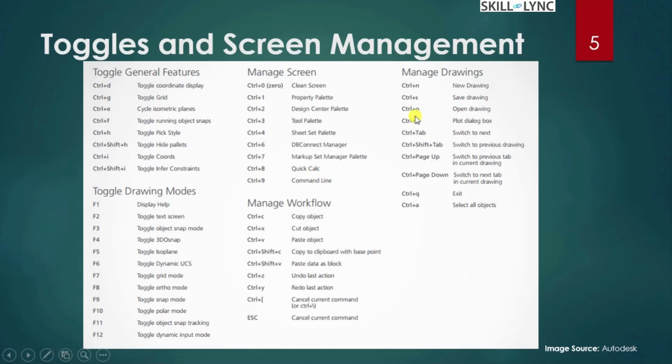And likewise, in order to switch between the different drawings, instead of selecting them manually, you can use Ctrl+Shift+Tab, Ctrl+Page Up, Page Down to cycle between the tabs that are available in the drawing. So next, again, the drawing moves that we saw in the one-key shortcut, and again in workflow for quick copy paste. So these are all overall workflow. Inside the drawing we still have the move option or cut option, undo option, all these things, but still we can use these shortcuts to quickly manage the workflow.